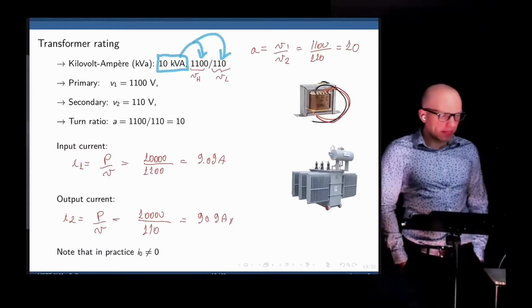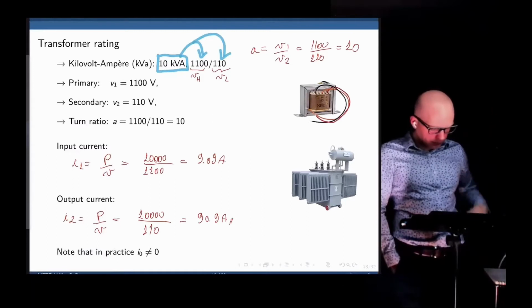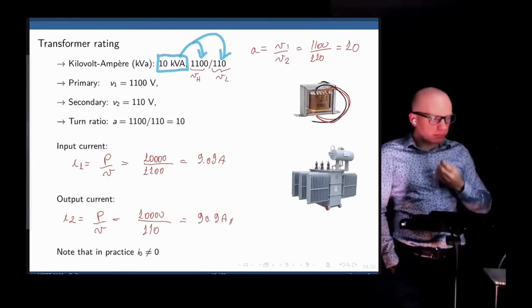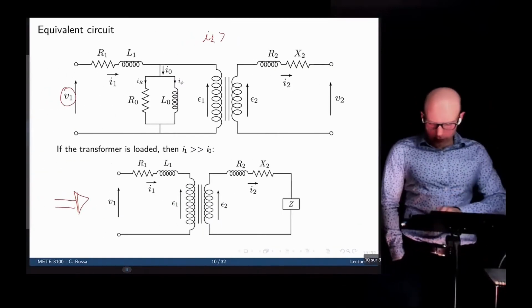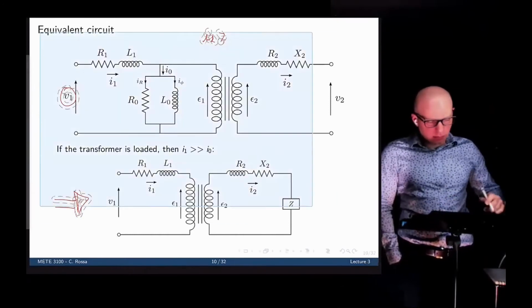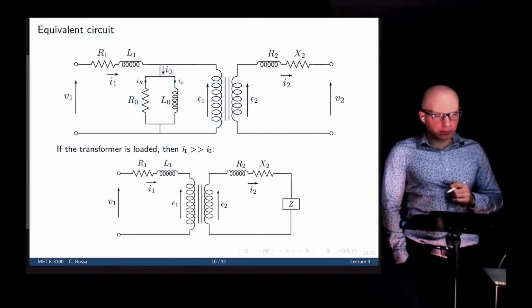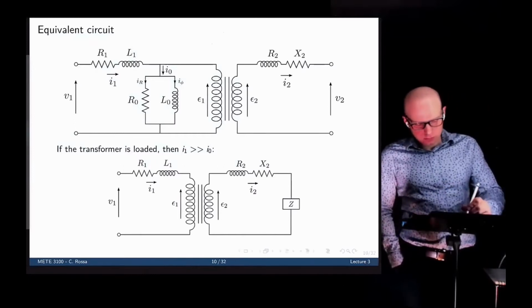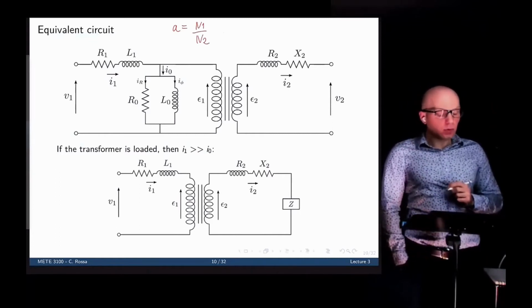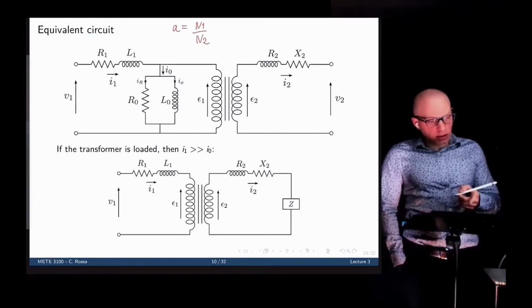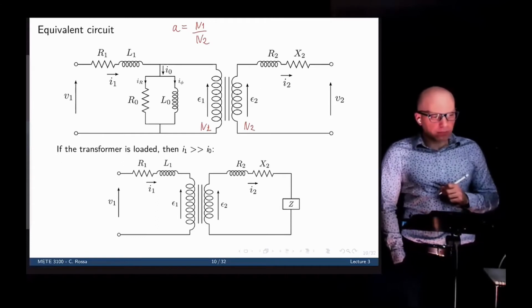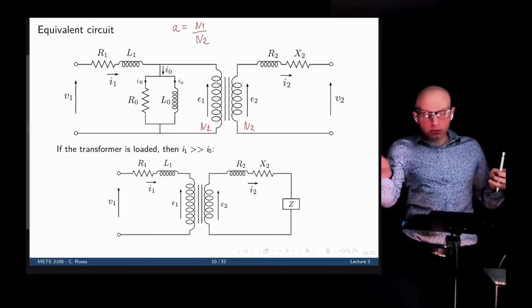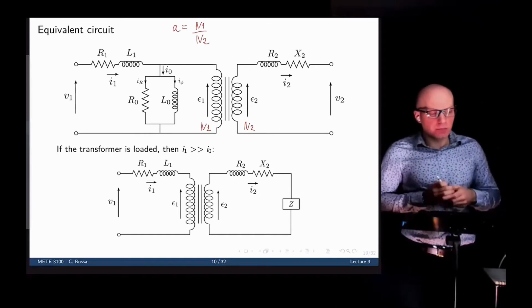So no. I have one more question. Just to clarify, between the ideal transformer and the practical transformer. In the ideal transformer, we identified the relationship A being the number of windings of the input over the number of windings of the output. That relationship A, it still exists even in a practical transformer, right? Of course. Yes, in this non-ideal transformer, we still have N1 and N2. Okay. And that's how we transfer the impedance from one side to another, right? It's through A, through that ratio.